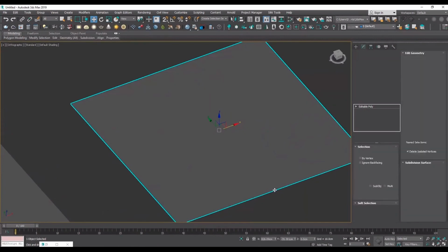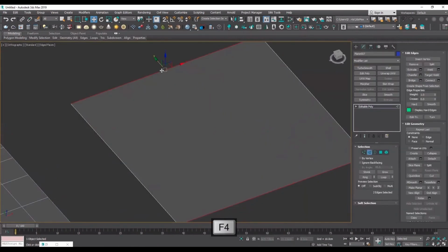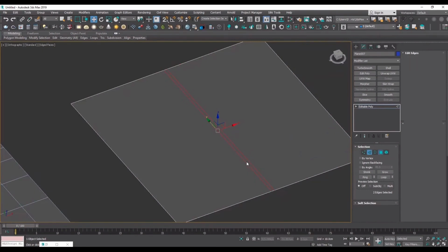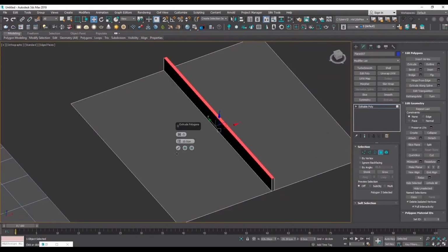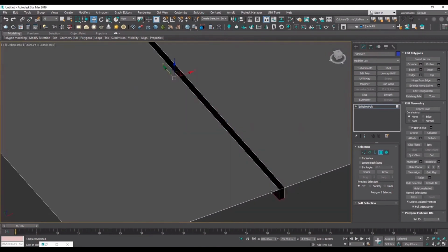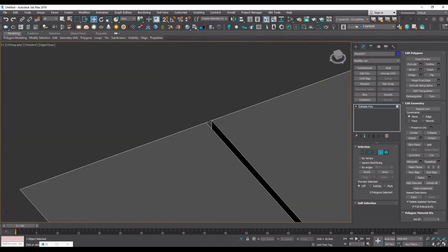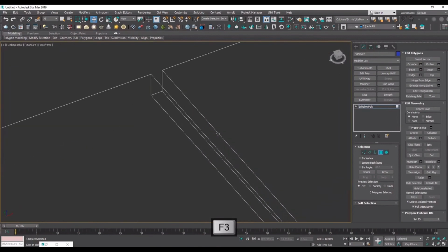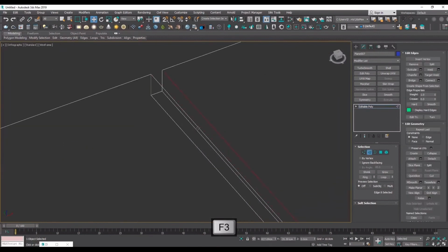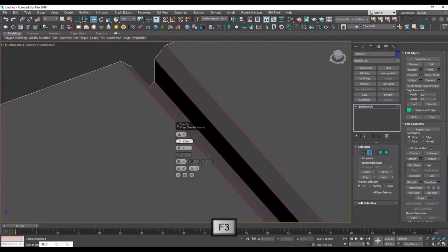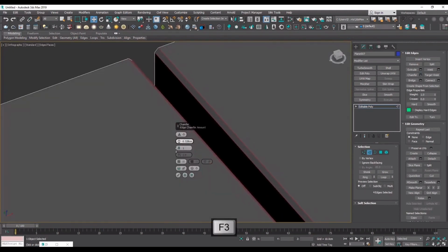Just like before, I put an edge loop by connecting the 2 edges. Do a chamfer to get another edge from it. Select the face in face select mode and extrude it down. Now I remove these 2 extra faces on the sides because we don't need them to maintain our detail. Like before, we have to chamfer the edges here 2 consecutive times. And just like that, we have made a nice little detail.